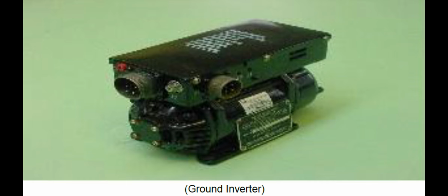On the ground, each switch is normally open. The switch is attached to a bracket on the lower end of the main landing gear housing and to the upper torque arm. The switch is actuated by the movement of the torque arms.